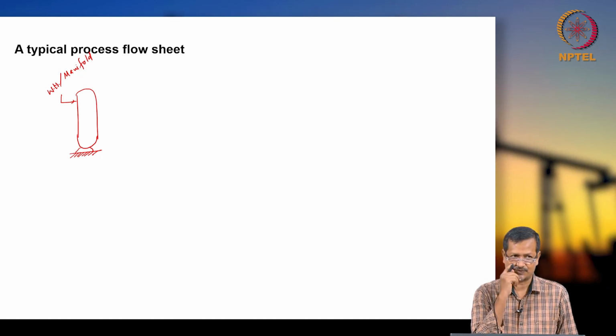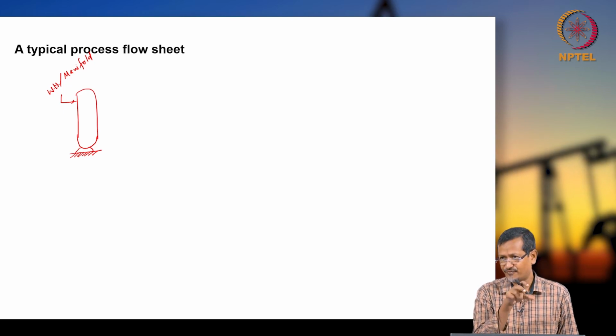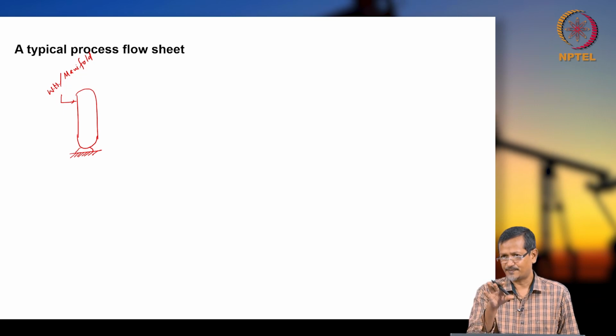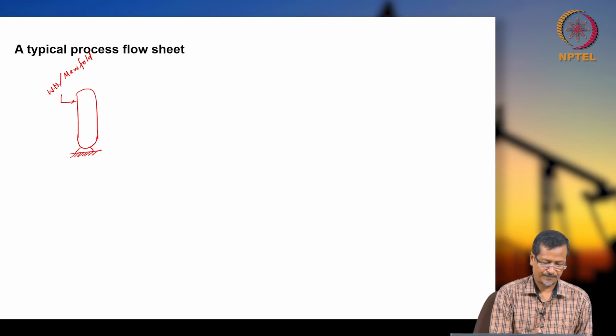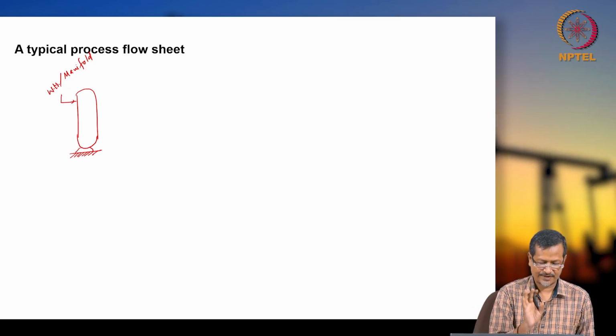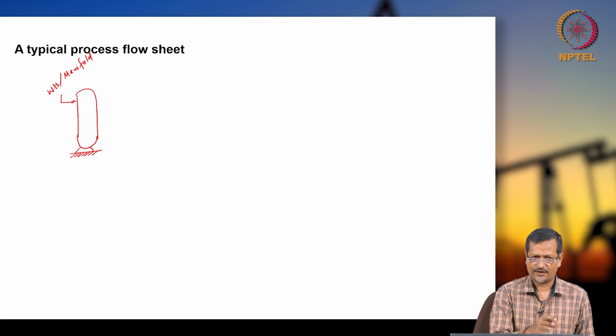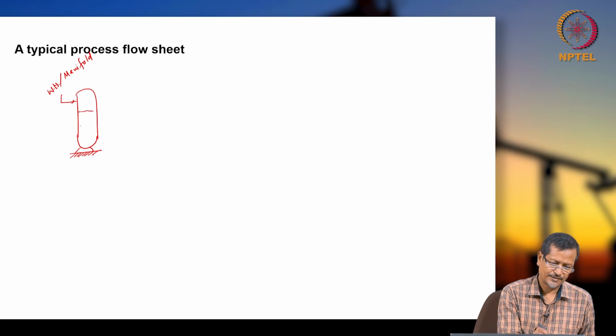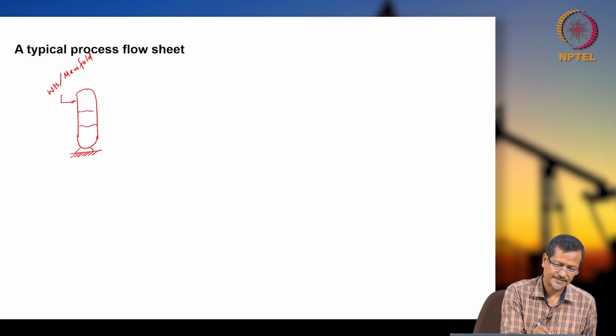So, how to manage this? You have to pass it through a manifold and control the pressure, then you put it into your vertical separator or horizontal separator. Let us say in the first stage I am giving one vertical separator; this may not be true, this is just a hypothetical thing. And let us say you are separating gas.